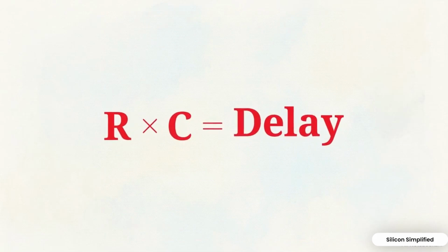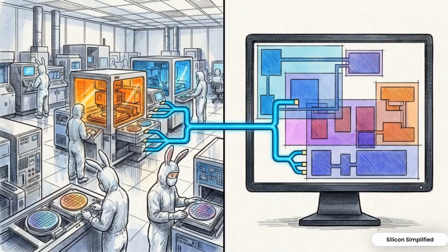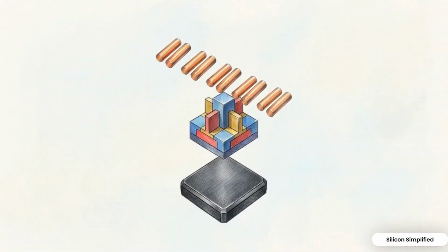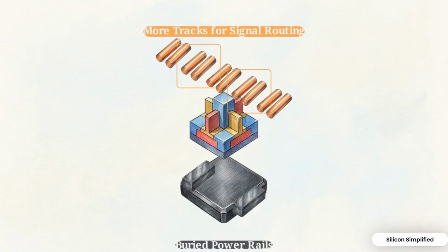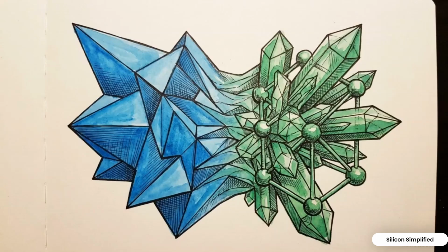delay of the design. This reality necessitates design technology co-optimization, or DTCO, where the manufacturing process and digital design rules are developed in tandem. Foundries use DTCO boosters, such as buried power rails, to move power delivery below the transistor layer, freeing up metal tracks for signal routing. Physical design at advanced nodes requires this direct co-optimization between digital layout and foundry-level material physics.